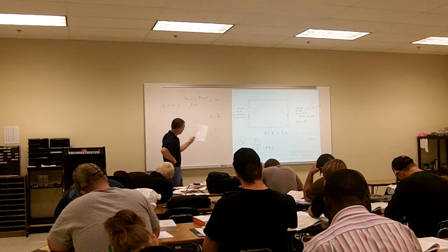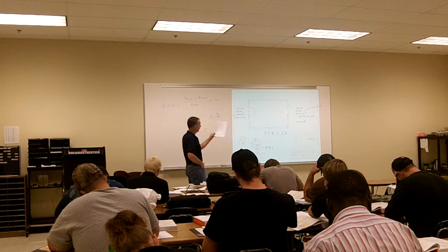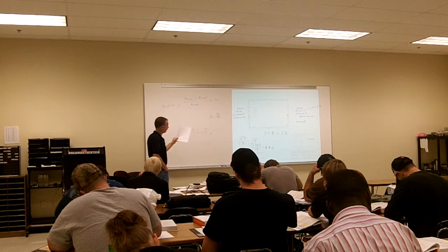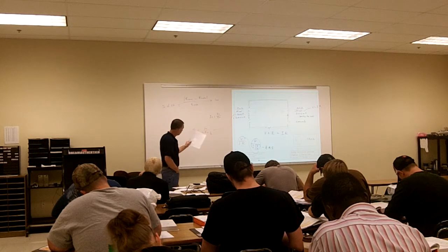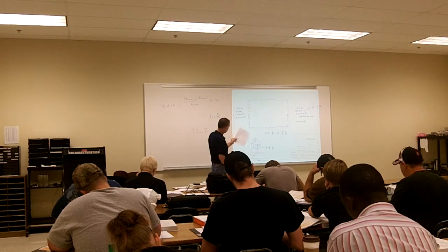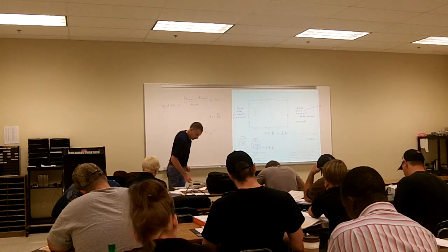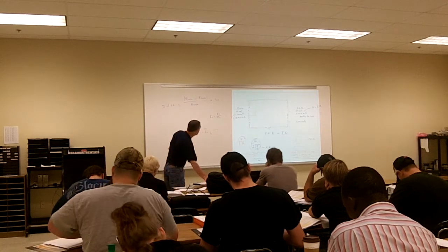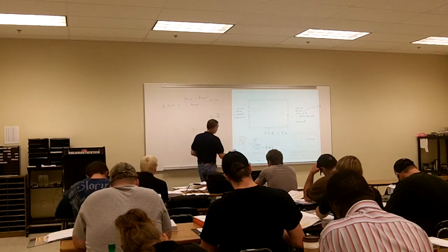When you're measuring voltage across the short, you will read approximately 0 volts. Okay? So when it's an open, it's going to be measuring your source voltage, and when it's a short, you're going to be measuring 0 volts. So we're going to say that for some reason our circuit's not working.